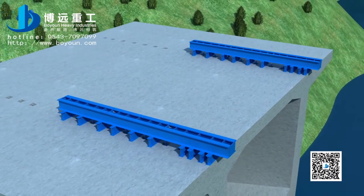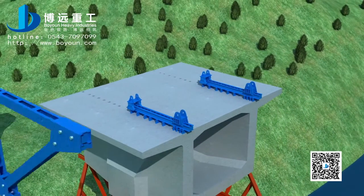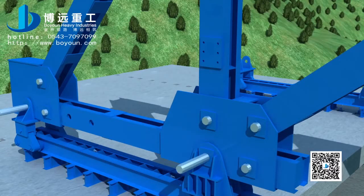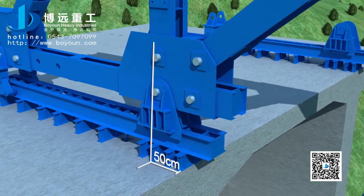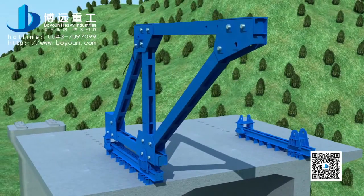Install temporary steel support. Completely install the reverse wheel fixing seat, front sliding bearing and diamond frame by pin shaft, and lift to the paved orbit. Adjust the front sliding bearing to the position 50 centimeters away from the edge of the girder end. After that, temporarily fix by chain block.